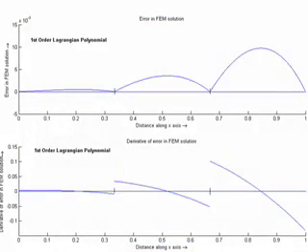What else can you note? You see that at the end points of the element, the derivative of the finite element solution is very far from the exact one. If you look at the error plot, this error is quite high at the nodes of the elements. This is a very important feature of the finite element solution. In fact, this is a drawback of it.